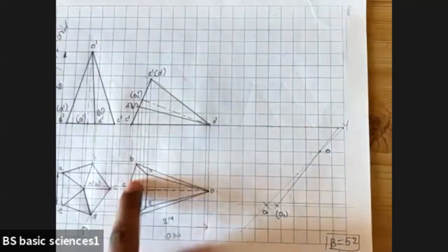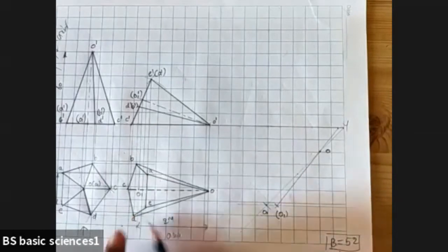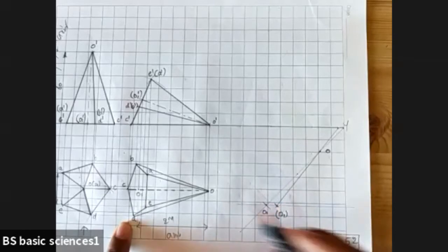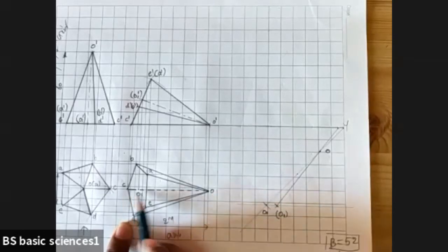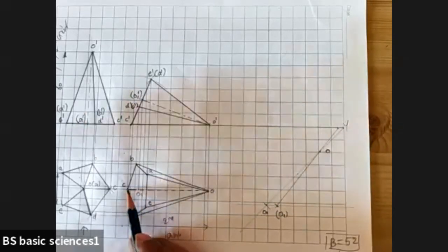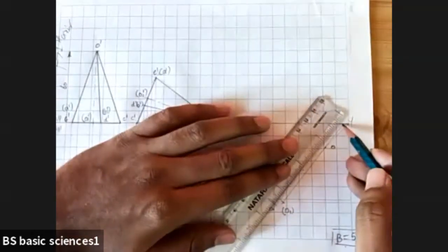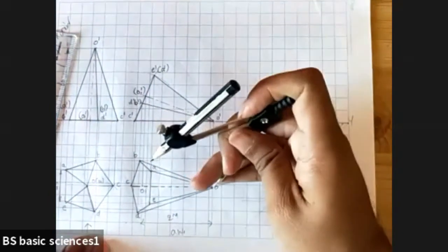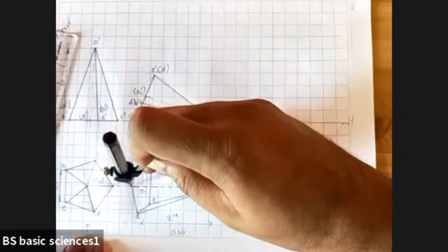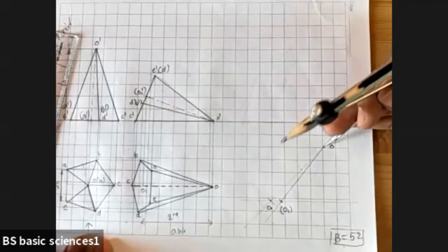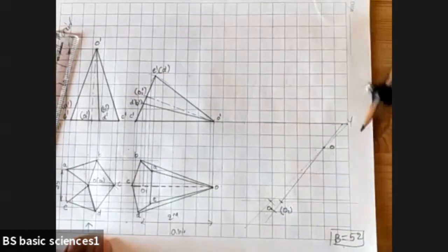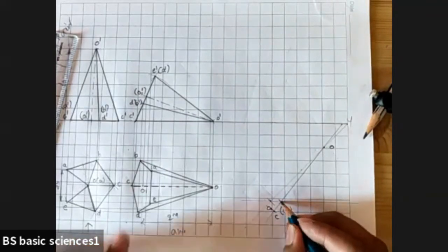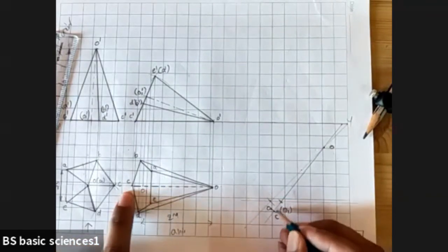First, we'll draw the pentagon. Now you listen. We already have the point O1, and we have the point O. And on the same line, we'll get C. So what you do is extend it. Measure from O to C. This is O. From here, O to C. So this will be a point C. This is your O1, and this is your C.